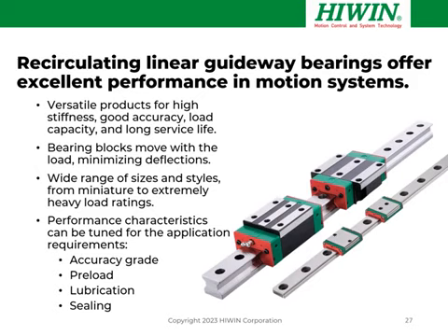They've been around for a long time, and the designs of linear guideways are highly optimized. So you can choose the performance characteristics that are necessary for your application specifically. For example, they're available in a wide range of accuracy grades. You can adjust the preload to get different stiffness or friction. Different lubricants are available for different unique environment conditions. For example, perhaps you're in a clean room, maybe in a vacuum, or perhaps you're operating in a high temperature.